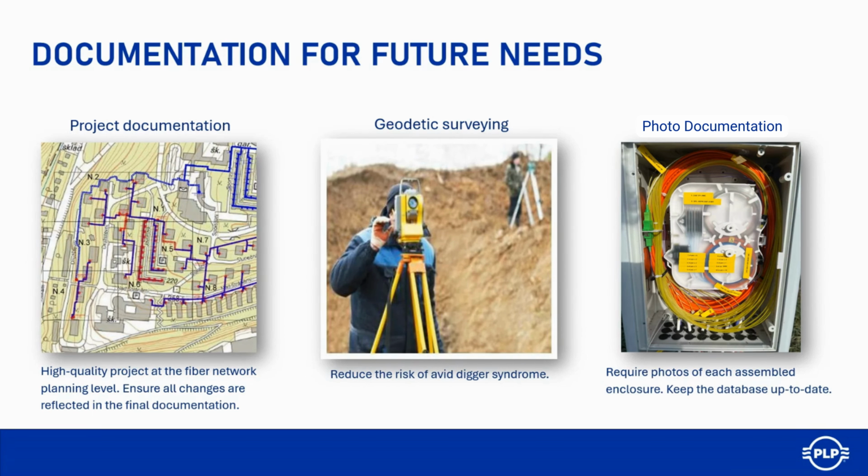And every time in the field, if there is any type of change, you need to reflect that in the final documentation. That's good for later reinstallation, adding the cables or whatever. So always when you do any change, it must be drawn in the final documentation, where you can see that actually there was a change.